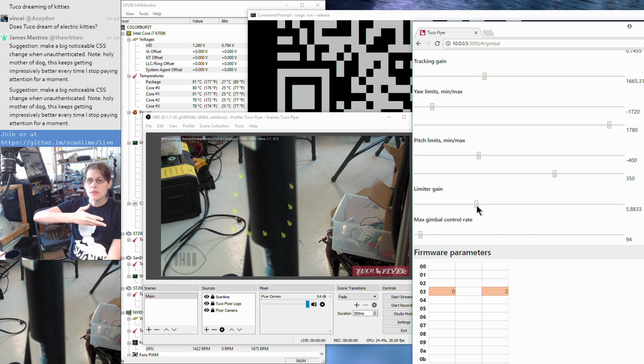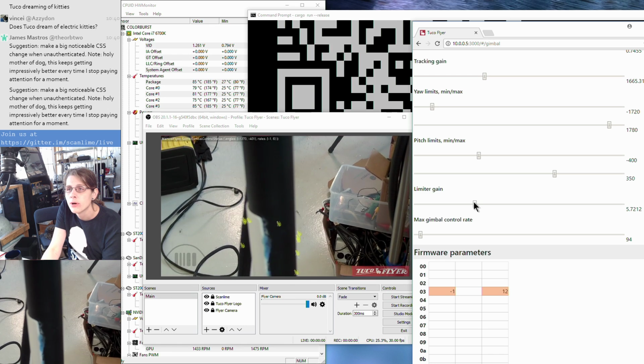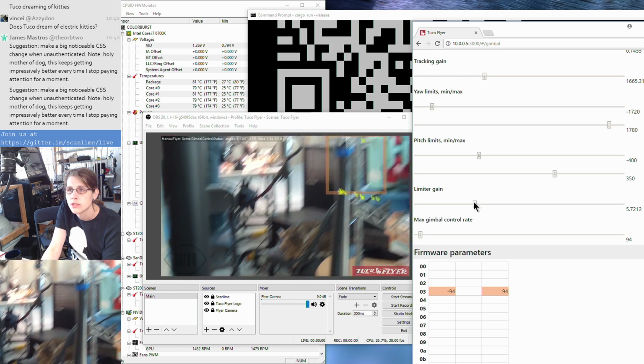It was almost like maybe that was a localized area where the gyro drift was, or like some nonlinearity in the system was especially bad and we had to get past that. I mean, there could be some other bug, but that looks like a nonlinearity in the response of the gimbal. So, yeah, it might not be just a matter of tweaking the gains, because you go too low and you get stuck because you can't overcome whatever that nonlinearity or whatever it is. You go too high and you just bounce. So, I think part of the solution here is to make the limiter soft.